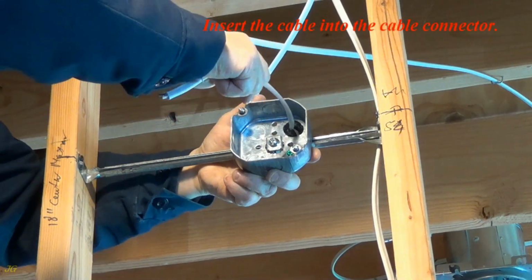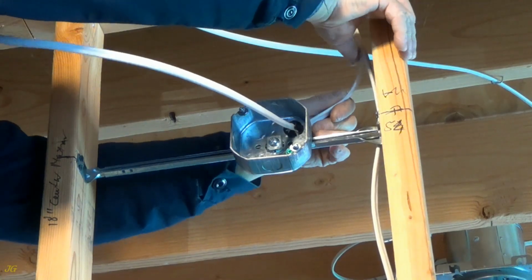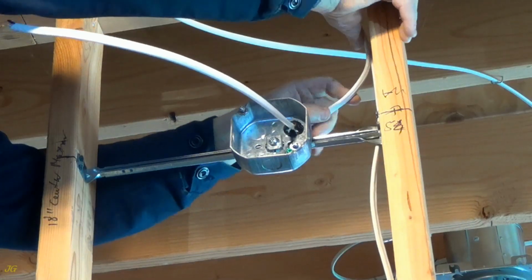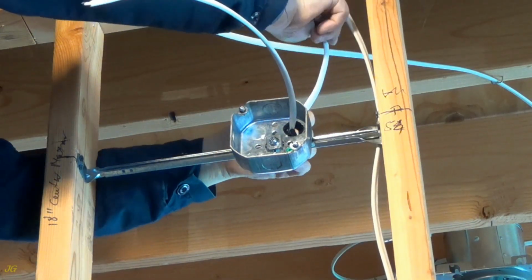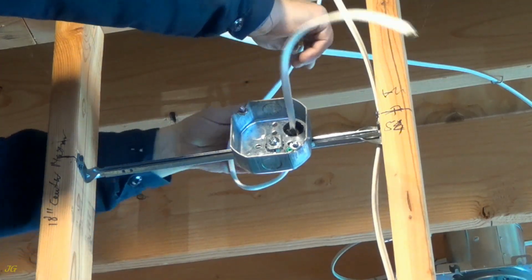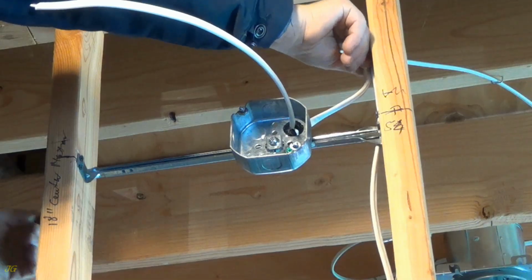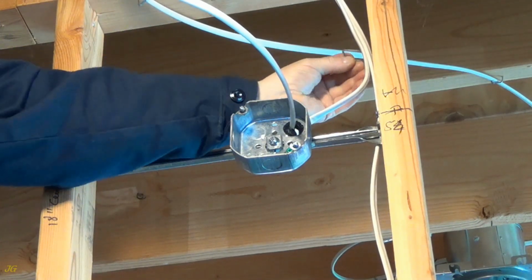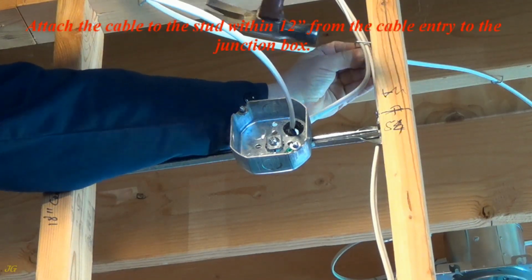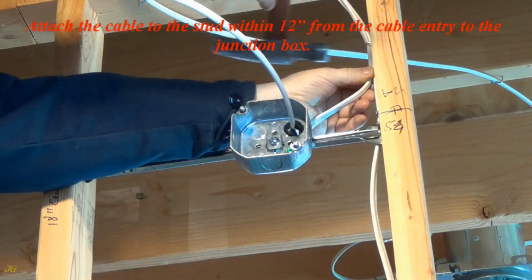Insert the cable into the cable connector. Attach the cable to the stud within 12 inches from the cable entry to the junction box.